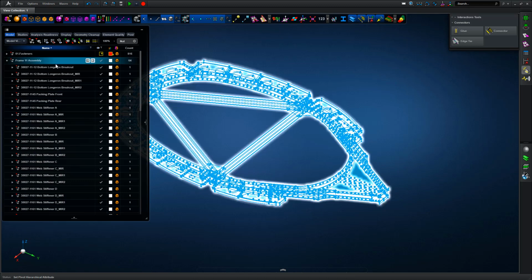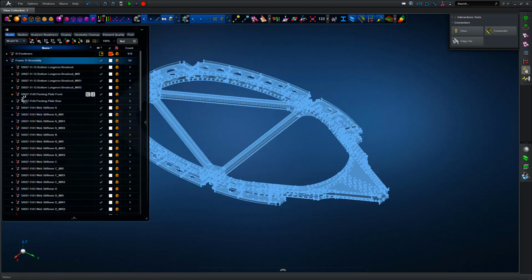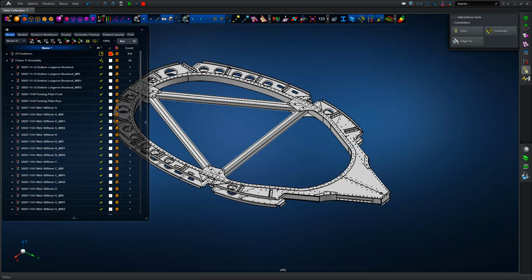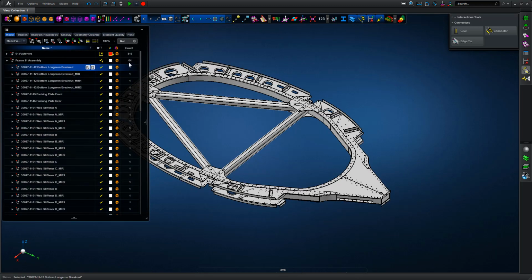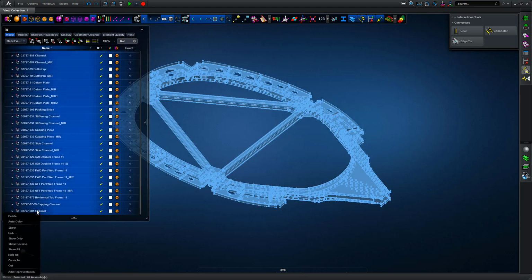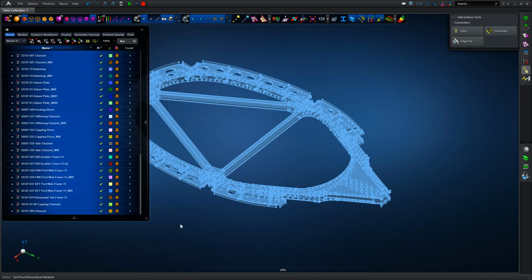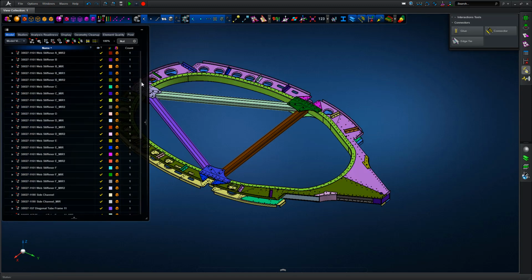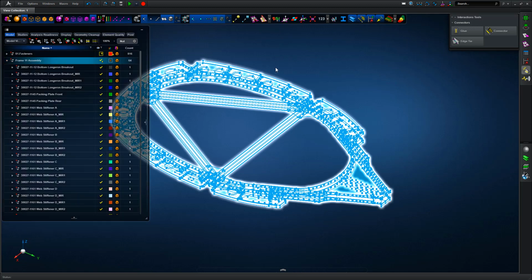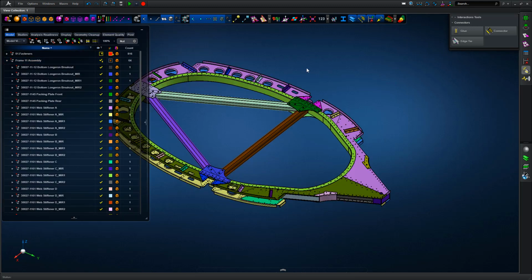So we take those out of view, and then we just show the frame 11 assembly, which is going to become our structural target, or target for the structural model build, and we've got all of those structural components highlighted. So we can auto color each entity within the tree to give us a unique color per part or subassembly, and it's a very nice display, or simplified display, in terms of what we've got with the overall definition.